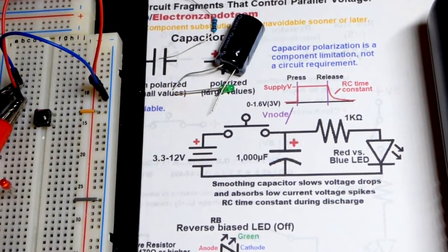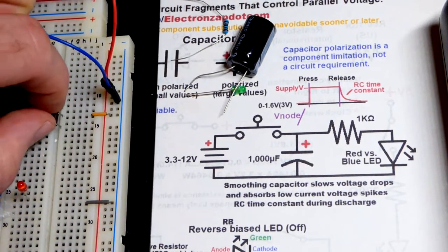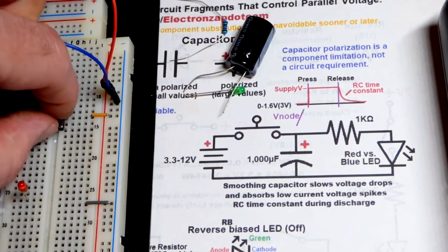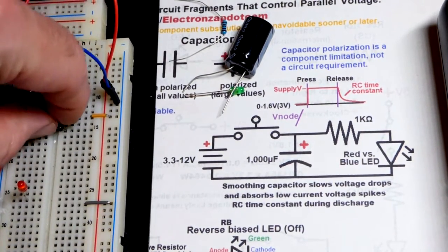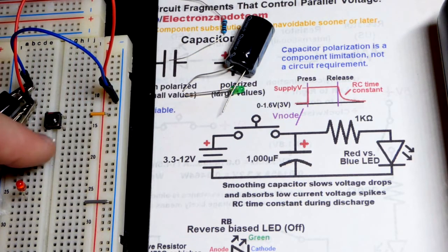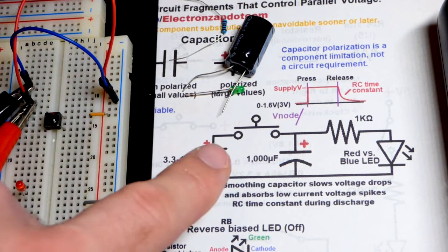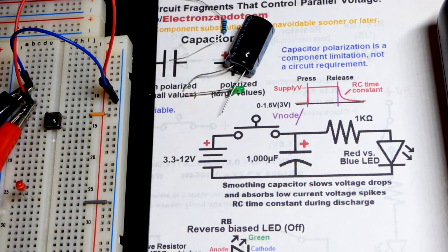We have in this circuit a switch, and I didn't mean to have it on the board yet, but we got the switch there. One side of the switch is a push button switch. We went over this component in the last video. Those top 2 pins are always connected. The bottom 2 pins are always connected. It kind of tries to squeeze itself out of the board. But there you can see that's connected to the positive side of the power supply.